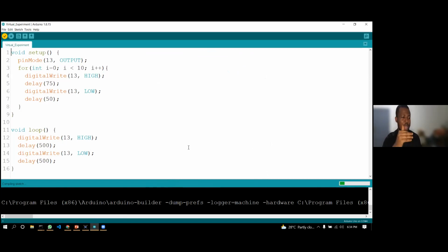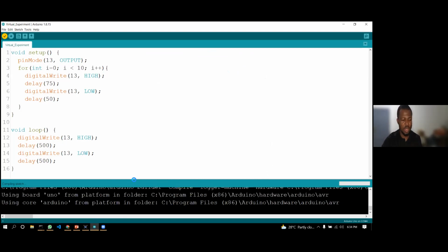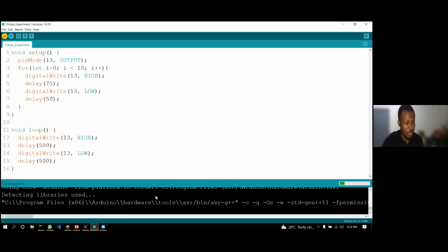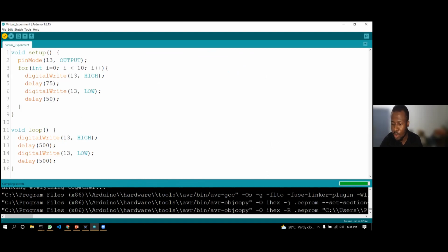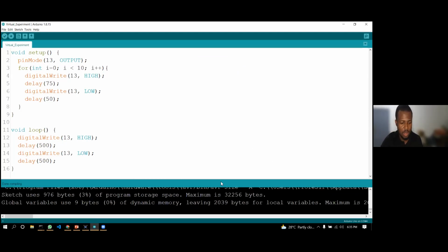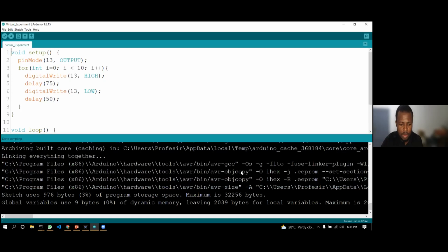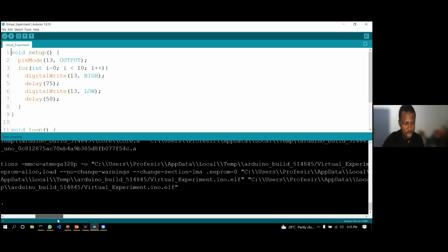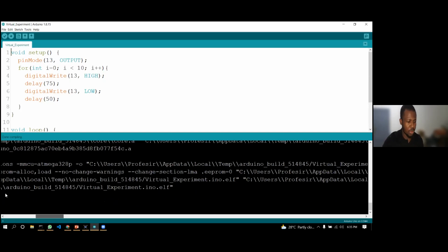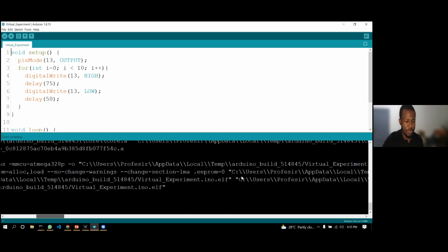All right, so I'm compiling the sketch. If you don't understand the code here, don't worry. By the end of the day, you would know what these things mean. Okay, so compiling, and then I have to close down some applications. Okay, so the program is compiled. Now I just have to link my output program to my Arduino. So let me copy this hex file.